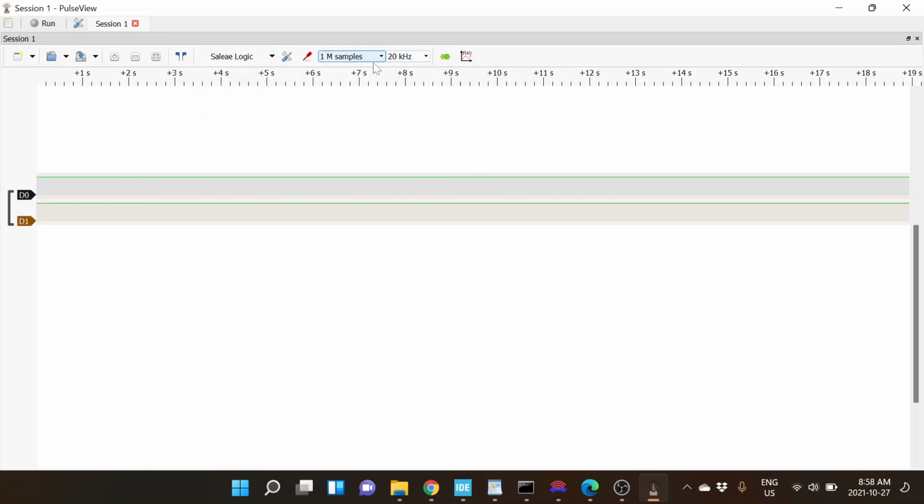And I am sending data on the UART. I said that 104 microseconds, that was 1 over 9600. Okay, and you'll hear 9600 baud and 9600 bits per second. Baud and bits per second are not exactly the same thing. One of the things we have is a start bit, and we have a stop bit at least, and we might have a parity bit. You can have 1 stop bit, 1.5, or 2 stop bits. So the number of bits per second is not necessarily the number of characters you get sent at the same time. But a lot of times people just kind of use them interchangeably.